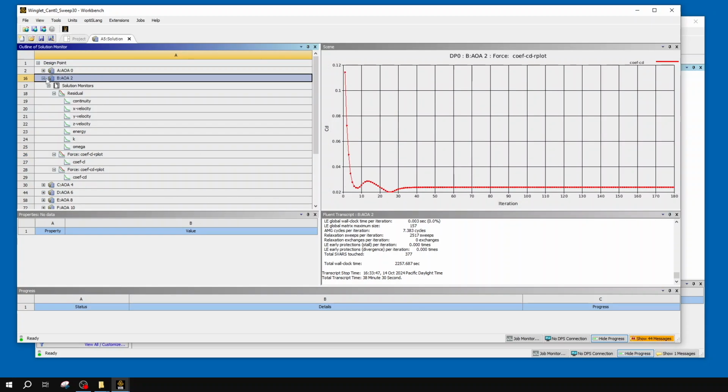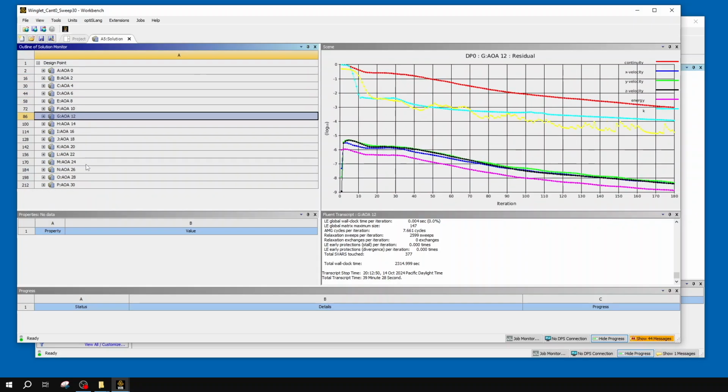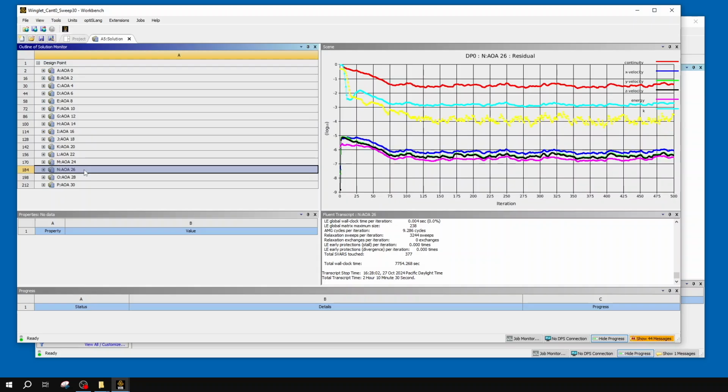Another option you might have, let's say I pop out to 36. In this case, it never actually converged. You can see here's -3, and we still have both continuity and, what's this, our K term. I'm not exactly sure what the K term is. It should be in the manual if you're interested, but it's just another measure of consistency between iterations.